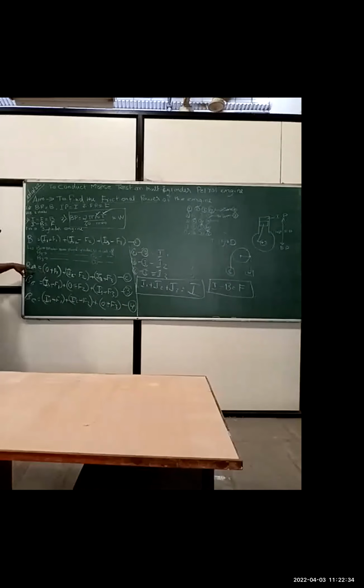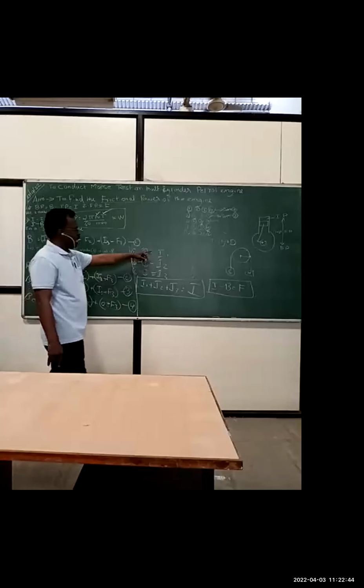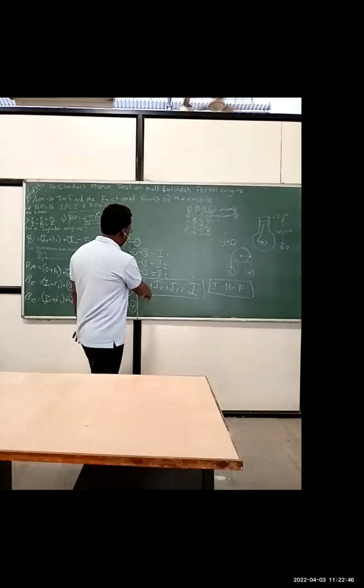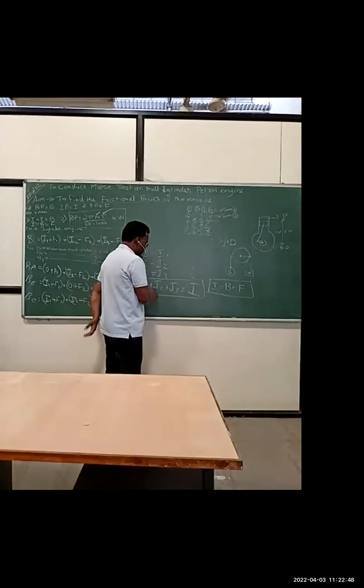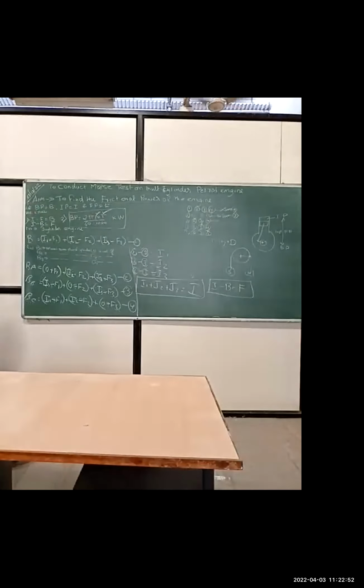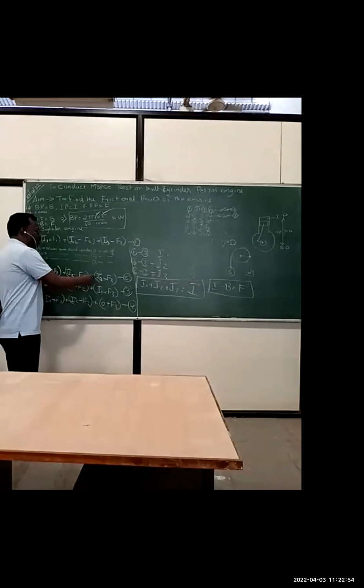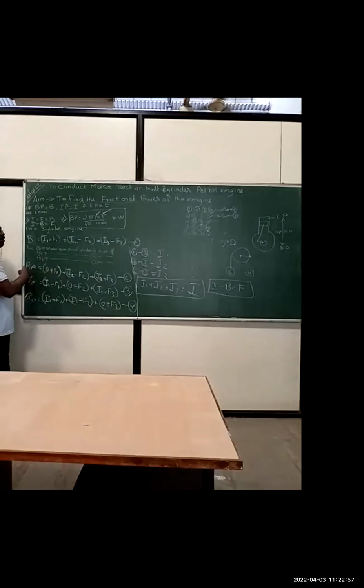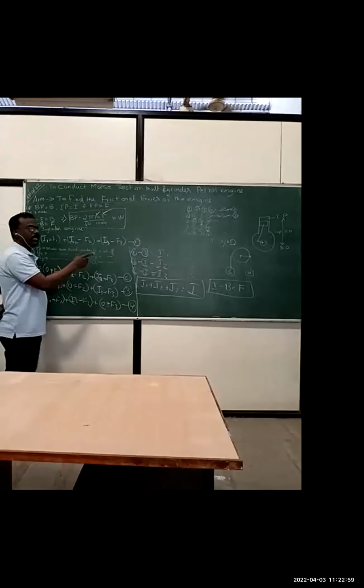So brake power corresponding to cylinder number 1 is I1. Here we are getting I2. So whatever power we are getting is I1 plus I2 plus I3. But what is I1 plus I2 plus I3? It is equal to I, which is the indicated power of the engine. Now here we have found out indirectly the values of I1, I2 and I3.